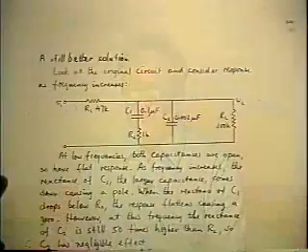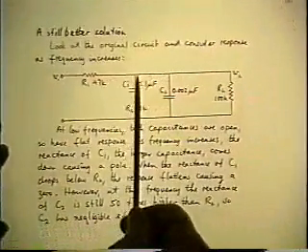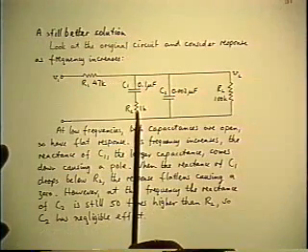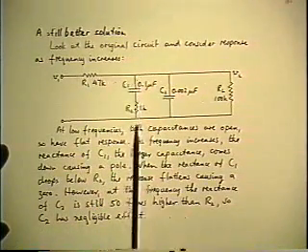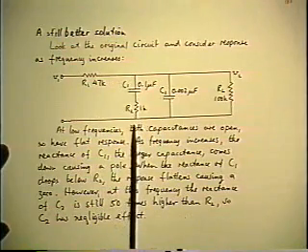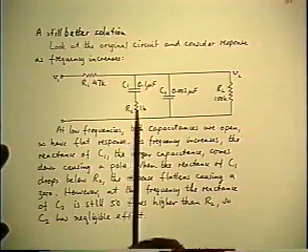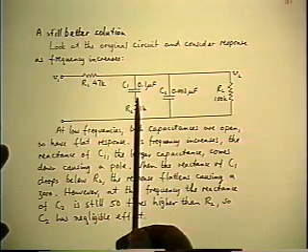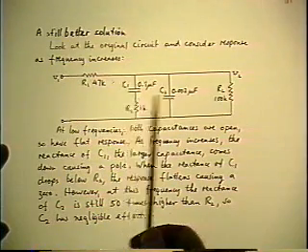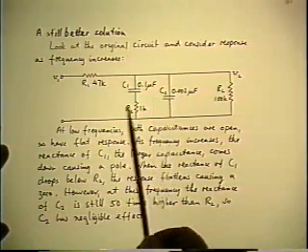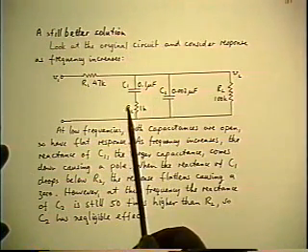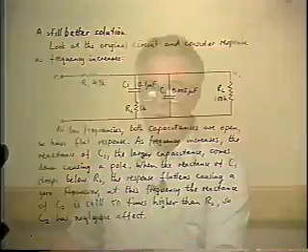The next thing that happens is the reactance of C1 comes down until it approaches 1K, in which case the total impedance of that branch starts to level off at 1K as the reactance of C1 drops below it. The reactance of C2 is still 50K, so it's still negligible. So as the reactance of C1 comes down, that slope in the gain will level off.